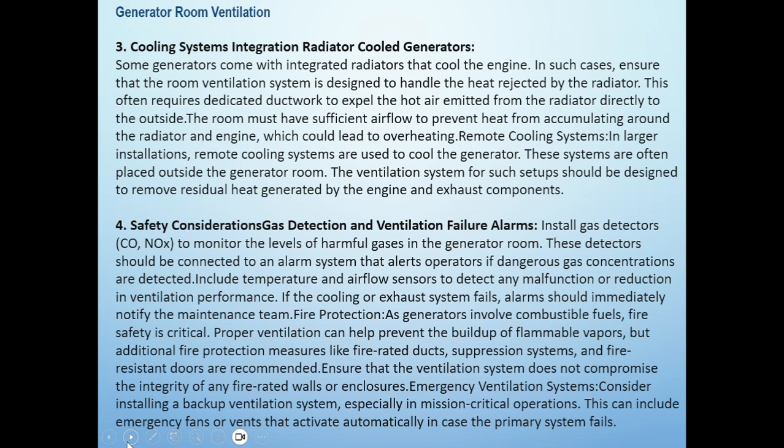The cooling system integration. Radiator cooled generators. Some generators come with an integrated radiator that cools the engine. In such cases, ensure that the room ventilation system is designed to handle the heat rejected by the radiator. This often requires dedicated ductwork to expel the hot air emitted from the radiator directly to the outside.